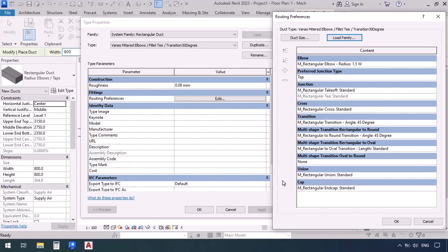But if you go to a whole project, you can see that little by little, when architectural, mechanical, and other items are added, the size of your file would become so big that it makes it hard to work with. So make sure which families you're loading. Don't just spontaneously add too many families. It's almost like when I go to a hypermarket and only pick up the things that I really need and then go to the cashier.